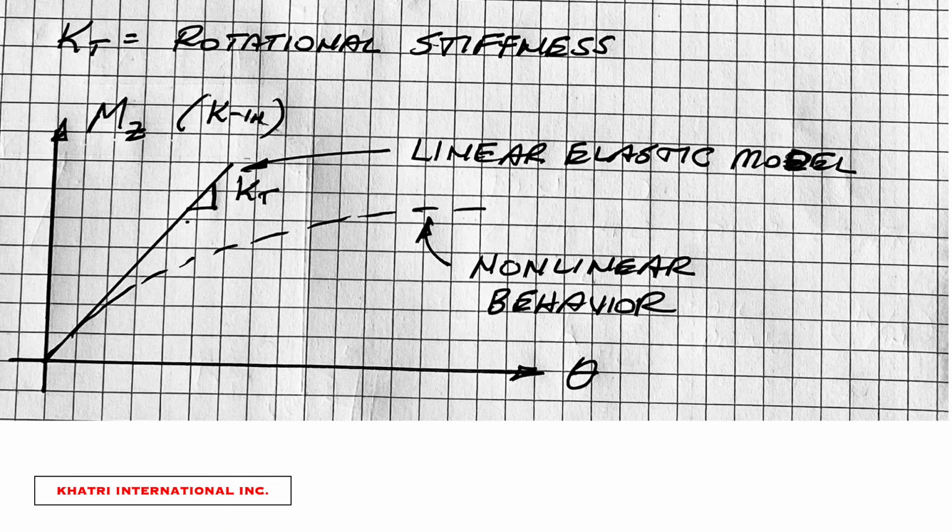And the rotational stiffness, which is the coil spring, same idea. The actual soil is highly nonlinear, and here we have on the vertical axis the moment rotation relationship, the rotational moment in kip inches versus the rotation of the foundation measured in radians. No specific numbers here because I'm only doing this analysis really to see just varying the numbers from infinity and degrading the rotational stiffness down to the point where we get some rotation, we get some deflection to see the effect of rotational stiffness degradation on the frame.